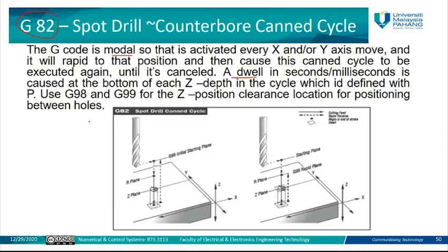because this also keeps the tool, or the head of the spindle, safe. When the drill is rotating for a long time, its temperature will go high due to the friction with the workpiece. So for that, they have different drilling cycles. It's not all the same, and it is not applicable for all materials. So it depends on the depth of the hole, and also the type of material of the workpiece.